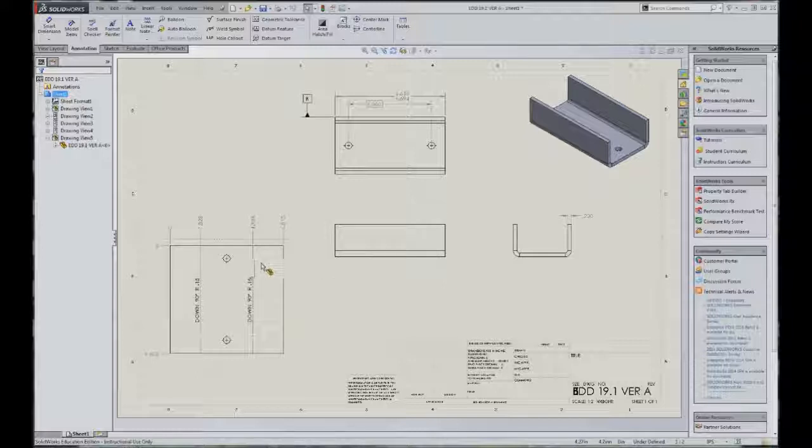So with a little quick math, I can scale all these drawings up a little in the TOPS software to get back to the 6.813 and make sure it's the right size. So that's another reason you put some overall dimensions in here, so they know that the software they've brought it into is going to make the correct part. Okay, some guys don't do that, and it ends up costing them money because they did not check to make sure that the file that was imported is actually the size that they use.